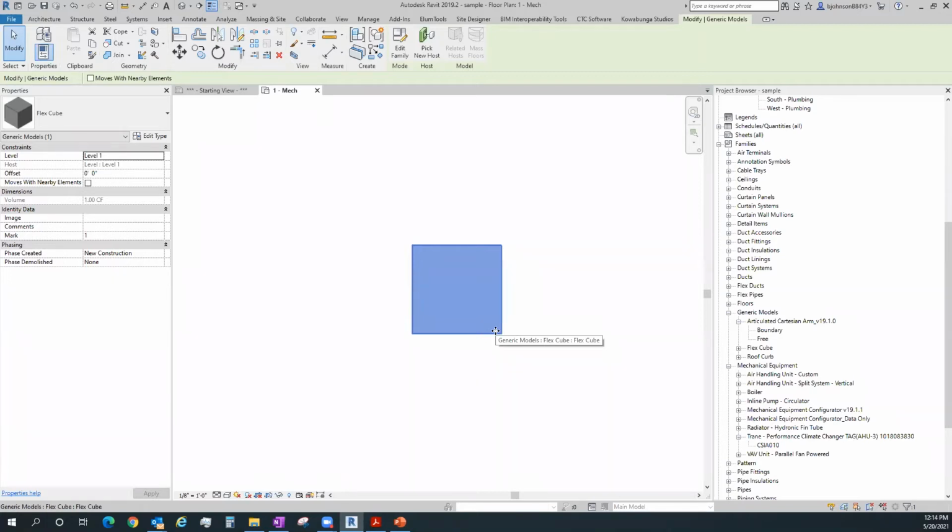Usually I don't like to go through all of that because it goes through lookup tables and type catalogs and everything else beyond. But in 8 hours, usually I can cover making a placeholder family, generating shared parameters, talking about family parameters, how to control those, how to embed nested links, and get those components with their parameters to work with the parameters in your main family. So if you need to pass through one parameter into another family from a nest, there's a way to do that and make it link correctly and schedule correctly.